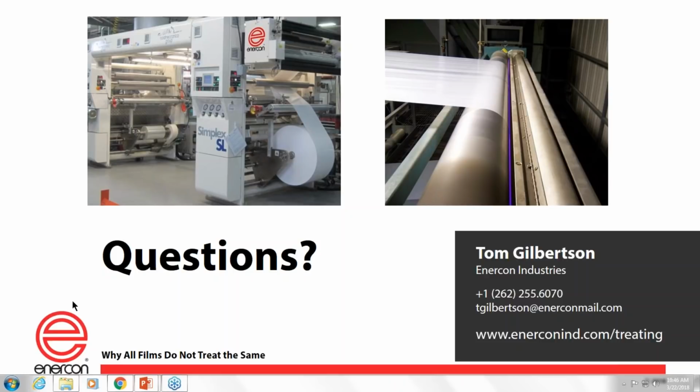Different materials have different decay rates. I'll give an example. In polypropylene film, for example, the decay rate from 40 down to say 32 may be quite steep and fast. Whereas on polyester, the decay rate from 56 down to the mid 40s, let's say, might take a while. It might be 6 months or something. So yeah, the film composition and what's in the film certainly has a significant impact on the dyne level decay rate.